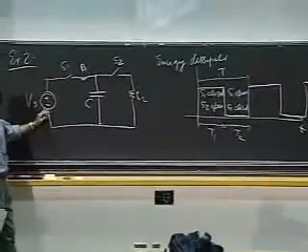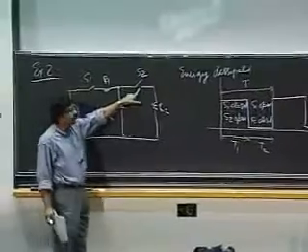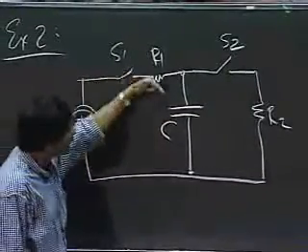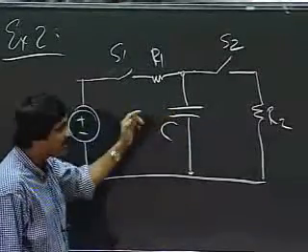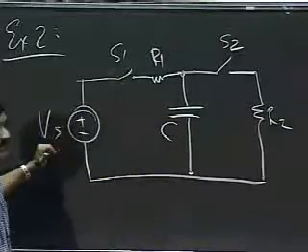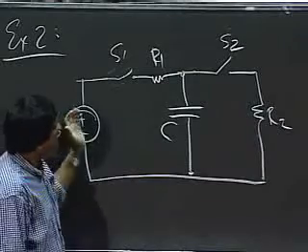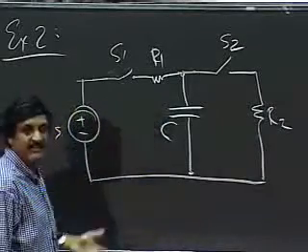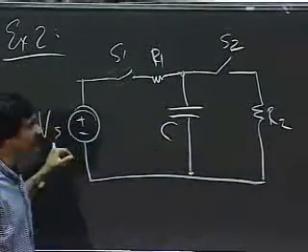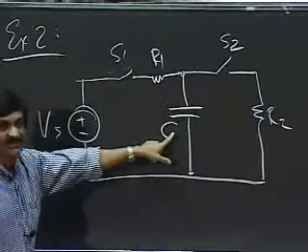So I start by putting a voltage source here, and I close the switch, ka-chunk. That's open. So start by closing this. So what happens? When I close the switch, Vs is going to charge up this capacitor, right? So I get current flowing through my resistor. So I'm going to be charging up this capacitor here. Okay? And then, let's say I allow T1 to be as large as possible. And so this capacitor is going to be charged up to all of Vs. So after a long time, this guy gets to be Vs on the capacitor.